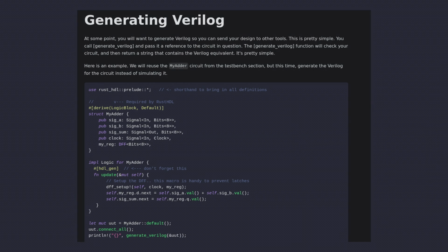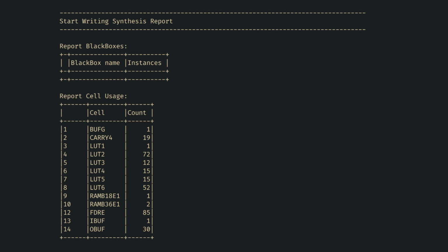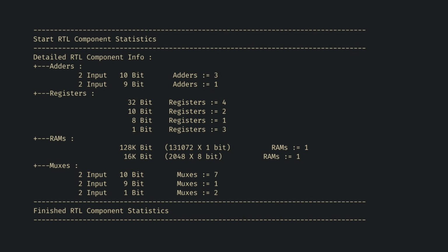Finally, in their book they have a chapter on generating Verilog, which is what I'm after. I change the signals in the block to match my board constraint files, and then write the top.v. Now, I run my Vivado script, and it becomes real hardware and my LED blinks. The output from Vivado is horrifically overwhelming, but is actually really cool. Specifically, you can see the utilization of the different subparts of the FPGA.